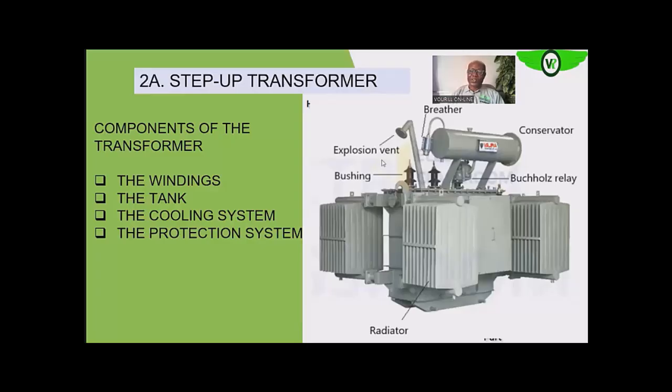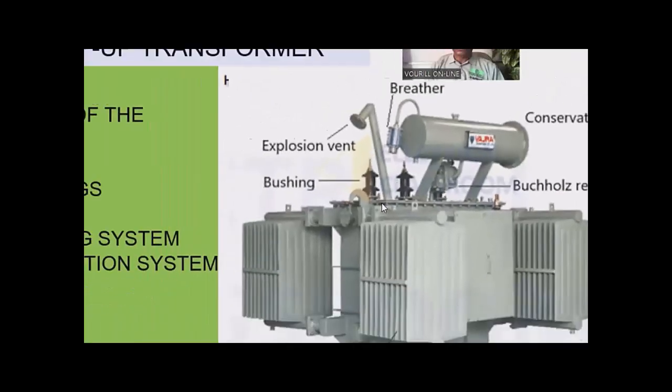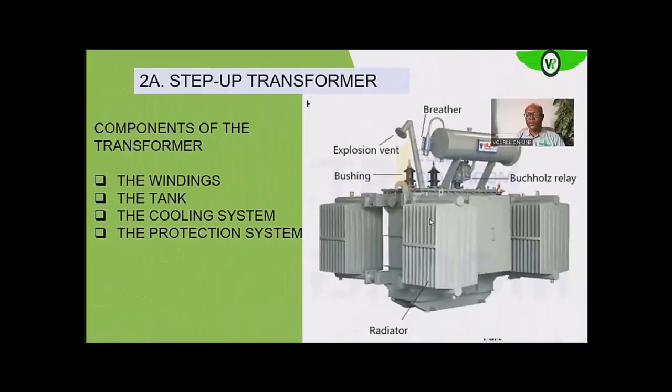Okay. So the bushings, like we said earlier, are meant to insulate the active part from the transformer body. And like we said before, when there are some faults within the windings of the transformer, that may cause arcing within the windings. And we know that arcing in itself is a very high thermal event, and that can cause the dissociation, the breakdown of the oil molecule, and thus generate hydrogen.